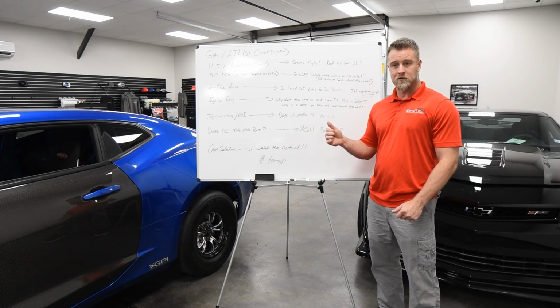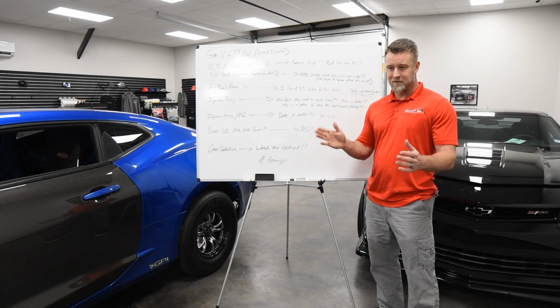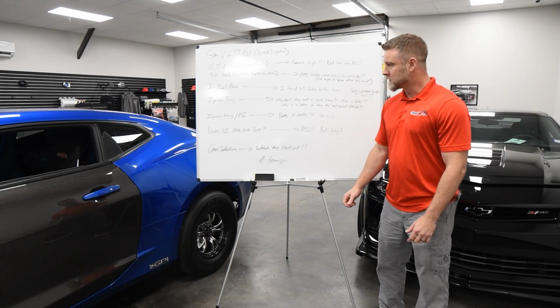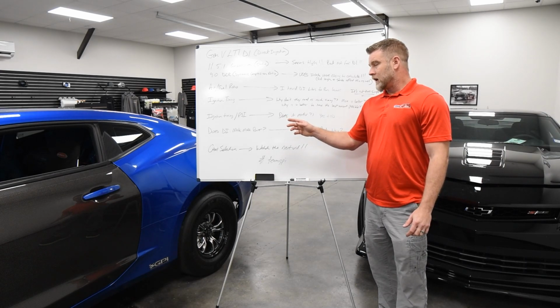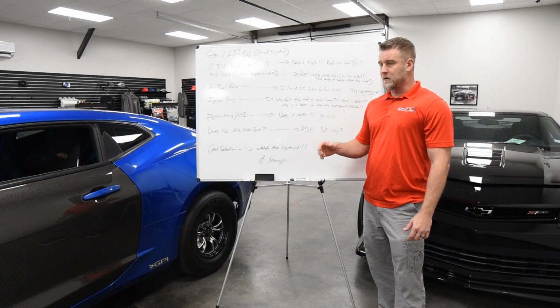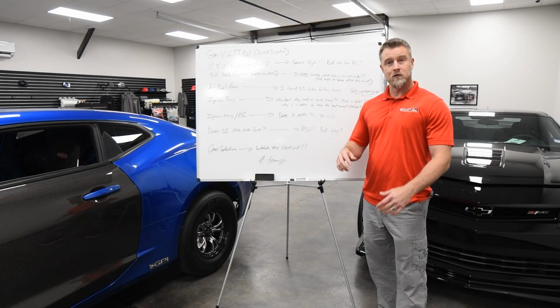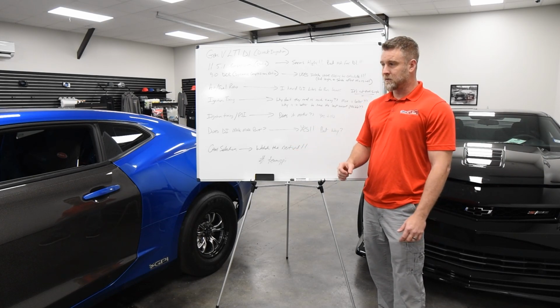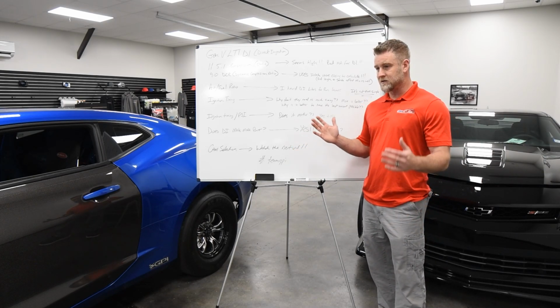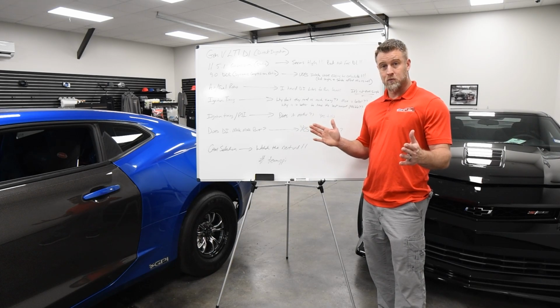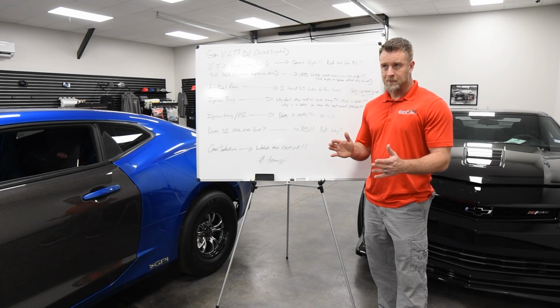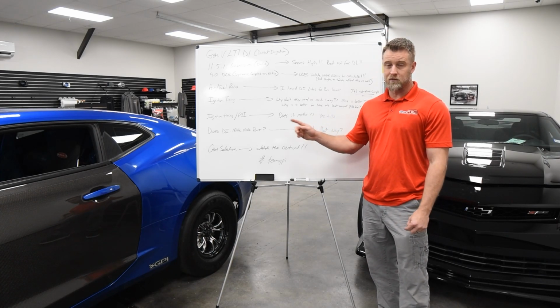When you turn the fuel pressure up, it gets more fuel in a shorter amount of time. So at some point, in our bigger combos, especially with the E85, we go to the LT4 fuel system to be able to crank the pressure and get that injection event pulse width as short as possible. But in terms of tuning the start of injection,